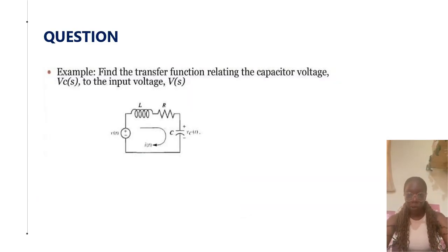This is the 21 and we will be presenting on transfer functions today. A transfer function is basically a mathematical representation of a linear time invariant system in the Laplace domain. They're giving us the ratio of the output to the input, and so it can help us represent dynamic behavior of systems such as control systems, mechanical systems, and electrical circuits, without actually solving differential equations directly.